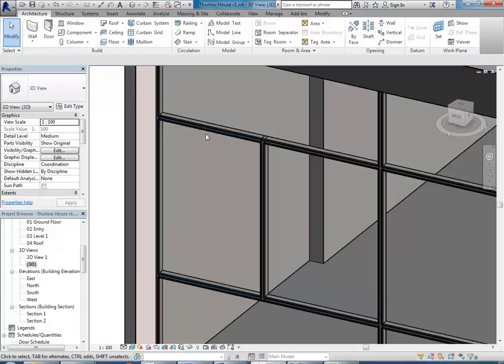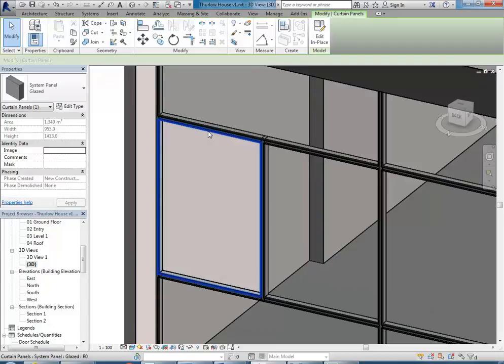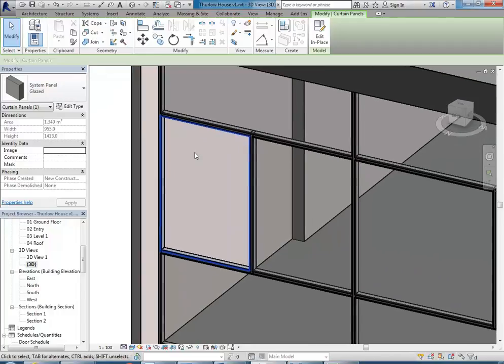So basically the technique is to move your cursor onto that edge and then just look at that bottom left corner until you see the thing you want, and then click. And it'll highlight it. Yeah, so you just got to keep your cursor where it is. No, don't click anywhere. So click into an empty space just so there's nothing selected. Just makes it a bit easier. And then move your cursor where you want it to select something. And then before you click anywhere, tab to get the different options. Only once you see the right option.